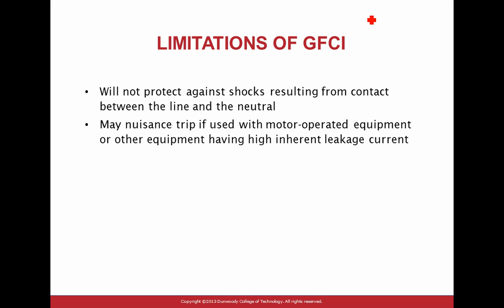If you have GFCI protection in your equipment, I don't know, do you have any GFCI on some of the equipment you use? Typically, if you have a process, you don't want that one because it could interrupt the process. If you have GFCI, make sure you understand that the GFCI will not protect you if you grab the phase and the neutral, like this. GFCI wouldn't even wake up.